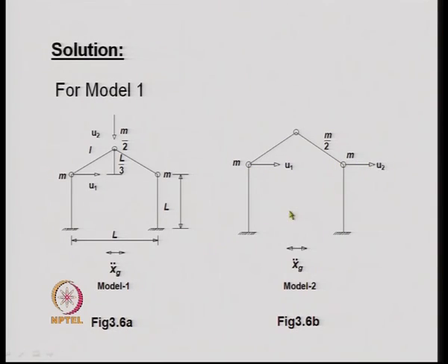So, there are 2 degrees of freedom because we assume that all the members are inextensible, and in order to maintain the inextensibility we have over here only 2 degrees of freedom. For example, if we wish to give a movement here, then automatically this one should move in the horizontal direction, otherwise this member will undergo a change in length.